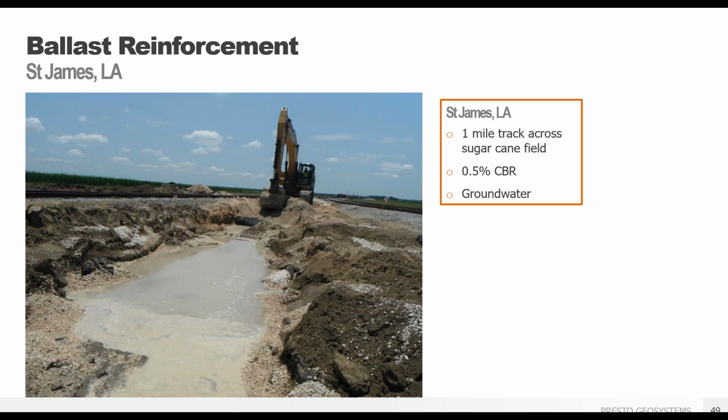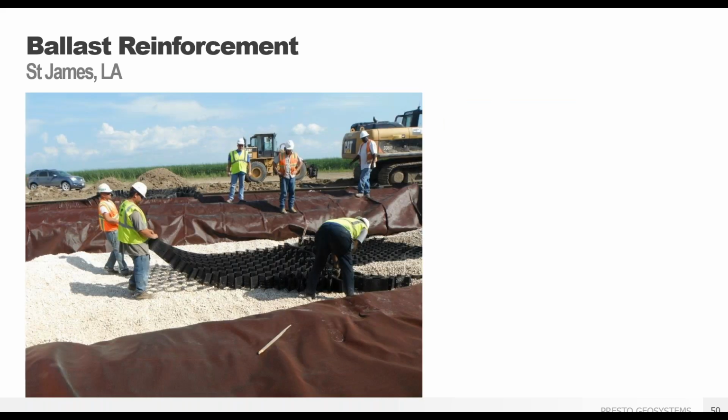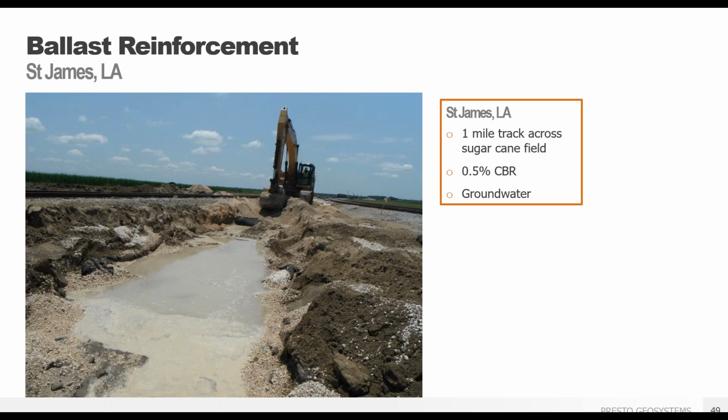Here's another project that we did a couple of years ago. This was down in Louisiana. We actually had to cross a sugarcane field. Really poor CBRs, you can see here, with high groundwater levels, CBRs less than 1. And you can also see how that track is between 2 tracks, so really the water gets stuck. It didn't really want to flow that far.